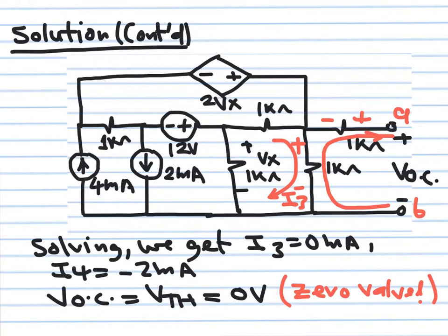Independent sources are the ones that give energy. Okay, and the rest, this is not really a true source. This is simply another component that enforces one more relationship between the voltage and the current, or the voltage between these two terminals and the voltage between these two terminals. But this one does not supply energy. So if I didn't have this one, didn't have this one, there's no Thevenin. So just remember, for circuits that do not have any independent sources, Thevenin is equal to 0 and the I Norton are equal to 0. Okay?